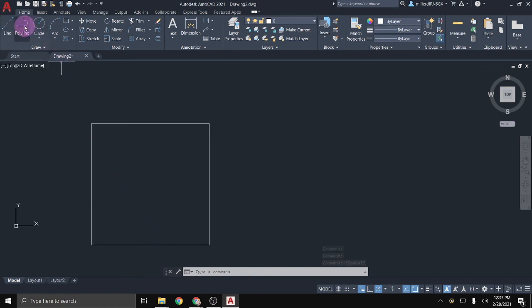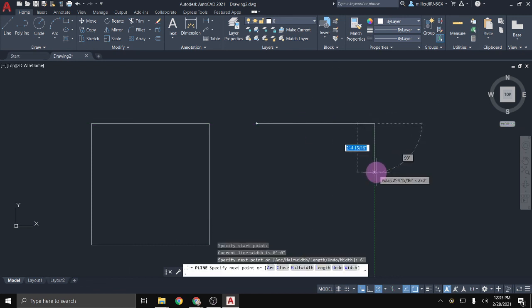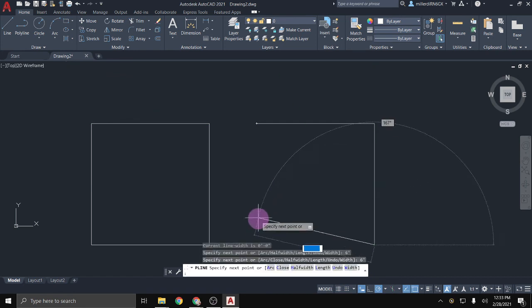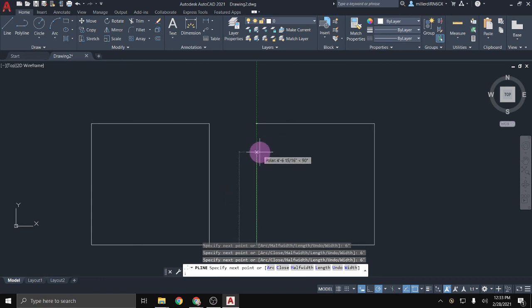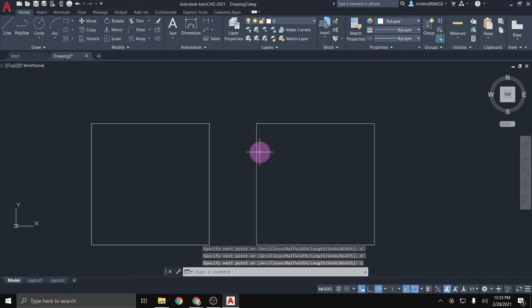If I do the same thing using Polyline, which is keyboard shortcut PL, I'm going to just hover over that endpoint just so these start lined up with each other for really no other reason. And I'll do 6 foot by 6 foot by 6 foot. And then I'm even going to put C to close rather than click to close it, and that just exits me out of the command. With the Polyline tool, this is all one connected piece versus this being separate pieces.